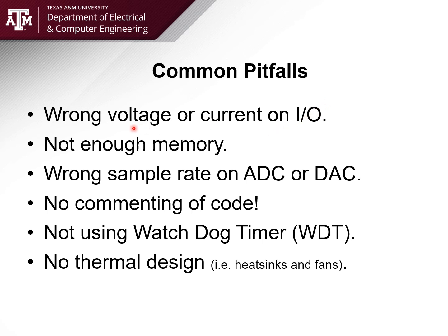You can't usually drive a relay coil directly off a microcontroller. You can't push a couple hundred milliamps out of a relay coil. That's where you need to use a transistor.